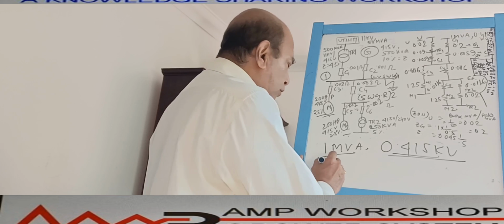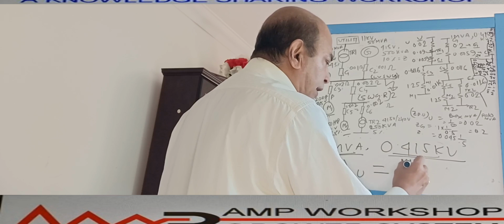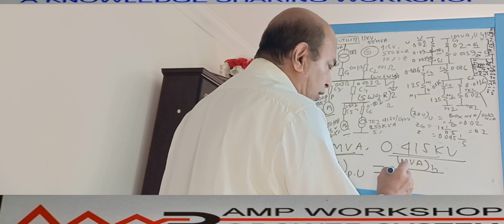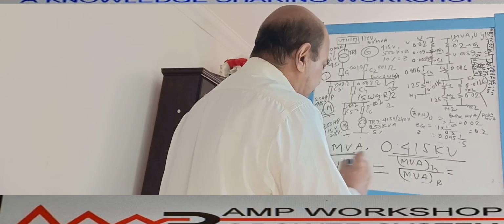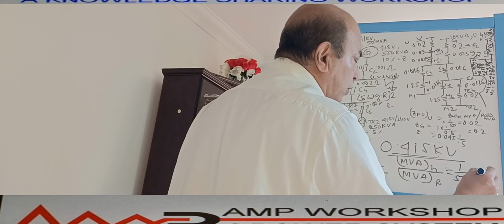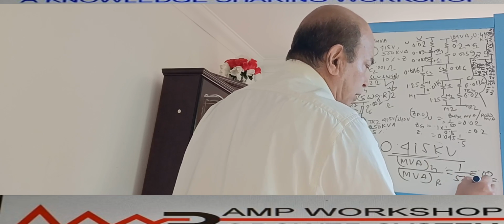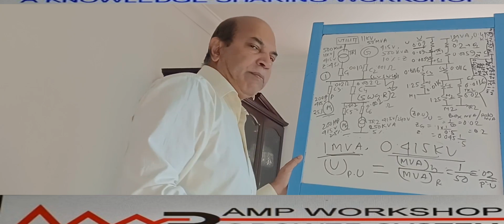Now for the utility per unit impedance, based on the 1 MVA base, that is very simple. The formula is base MVA divided by rated MVA, or short circuit MVA. So here the base MVA is 1, and the rated MVA is 50 MVA. That will give you 0.02. That is 0.02 per unit. That is the impedance. That impedance we have represented over here, 0.02 per unit impedance.